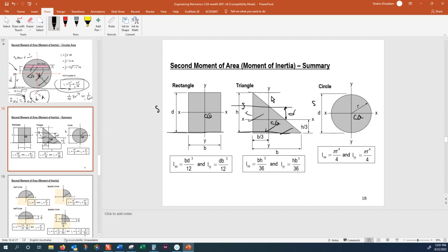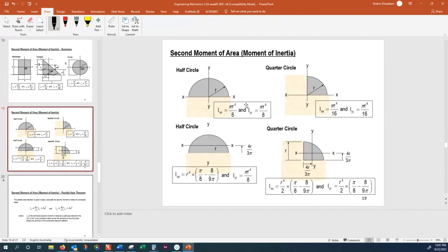of bending. Also, in the formula sheet in the exam, you will be provided the moment of inertia for a half circle, a quarter circle, and a half circle in which the coordinate axis is at some distance elsewhere. So in a sense, this is not a standard, is it? Because this is not through the center of area. Whatever you are provided in the formula sheet in the exam is a standard, and if what you want is different from that, that makes it non-standard.